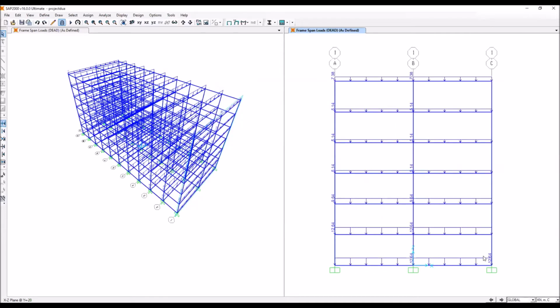So this is our load that has been assigned. We calculated the distributed load on each beam for each case: the roof, the ground floor, first floor, third, fourth, and fifth floor. So this is how the load looks. For the manual calculation, we are using the moment distribution method, which is the subframe analysis.